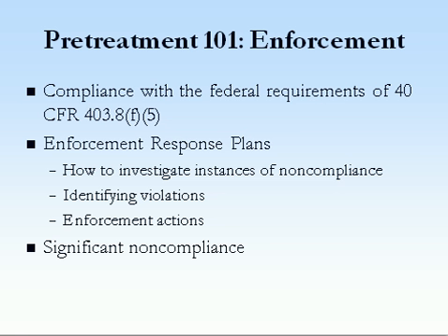And identified last in this outline of required components of an approved POTW pretreatment program, but certainly not least, is the POTW's ability and procedures to conduct an enforcement program. 40 CFR 403.8 F5 requires a POTW to develop and implement an enforcement response plan. This plan must contain detailed procedures indicating how a POTW will investigate and respond to instances of industrial user noncompliance.